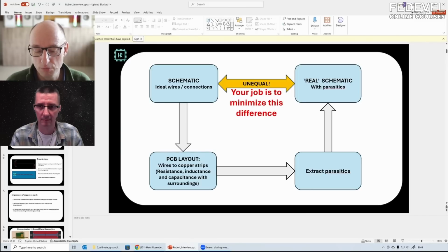So there's so many applications where you would think, a few nanohenrys, that's not going to matter, but it can actually completely ruin your performance. And I think that is something that is greatly overlooked, and why a lot of people think that this whole grounding stuff is a little bit of black magic. But if you understand the frequencies you're dealing with, and everything is basically much more wideband than you think in many situations, then you understand that these small values are really a problem.